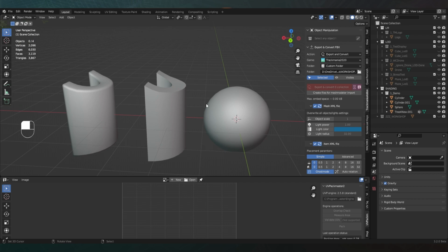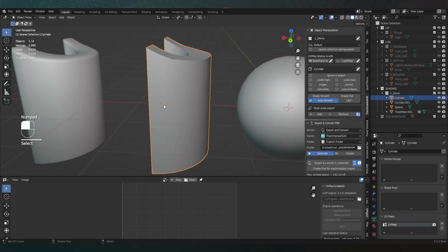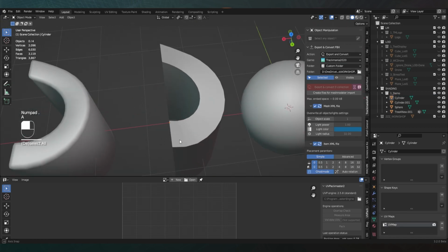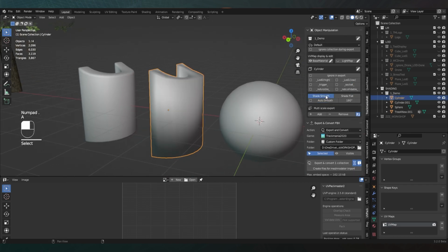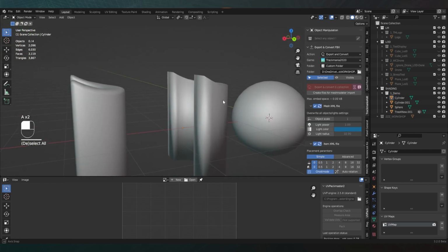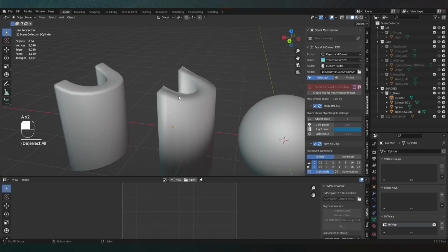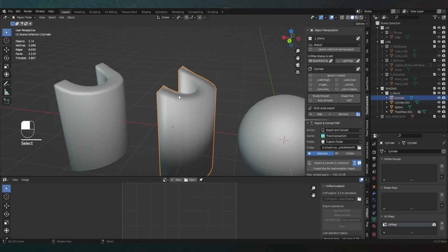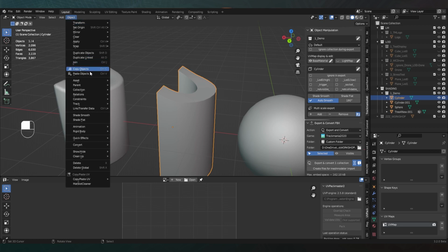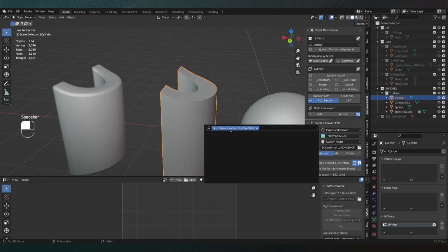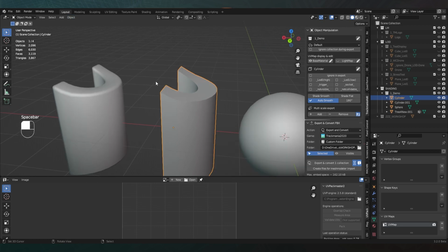when you have objects that rely on smooth shading and flat shading at the same time. So don't ask me what this is. This is just a random mesh that I made, but you will see if we just rely on smooth shading, it might look like this, and we don't want that. And there are two options again to take control over that. So there's an option called auto smoothing. You can enable it in the plugin, or I think you can type it up as well. I don't really know where it is in the menu right now.